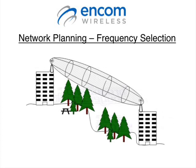The following picture shows the concept of the Fresnel zone. For this particular example, we have selected appropriate frequencies for each of our endpoints. The Fresnel zone is going to be this football-shaped path in between two nodes. Notice that the closer you are to your node, the smaller your Fresnel zone is going to be. So if you're going to start to have longer distances in between your two nodes, your Fresnel zone is going to get larger.